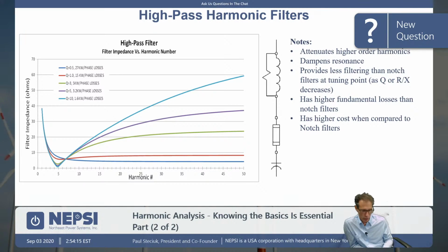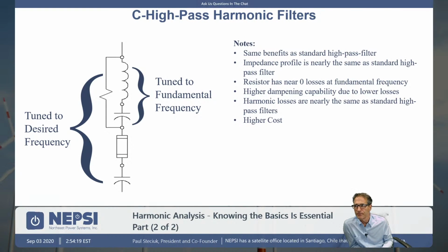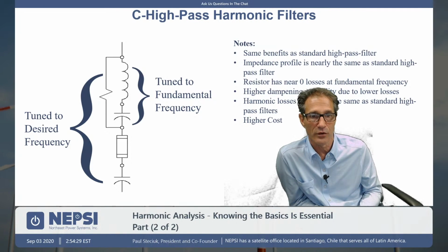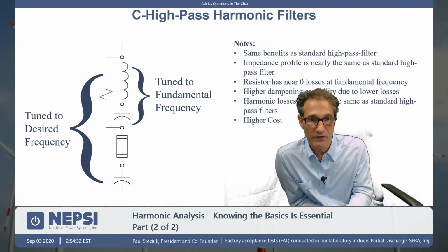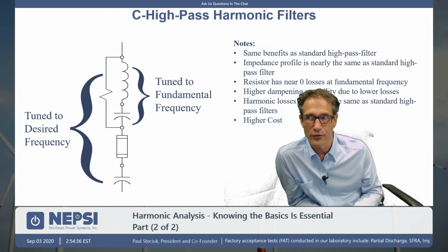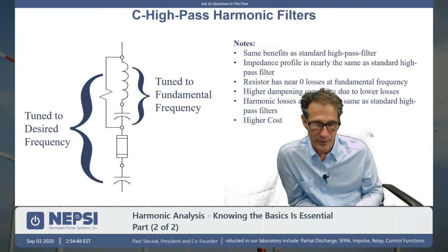So for the most part, we have determined that from our experiences, third harmonic filters are not normally required. Your statement that there's zero sequence is, in fact, what we have also seen. So in other words, we've installed a lot of filters. Sometimes we see the resonance creeping back towards a third. We get concerned about it. Normally we have what I would call a backup plan if I do have a third resonance issue. But we have yet to see really this third resonance phenomenon occur.